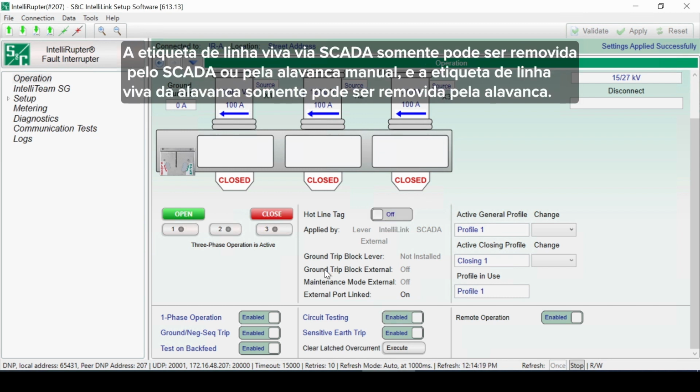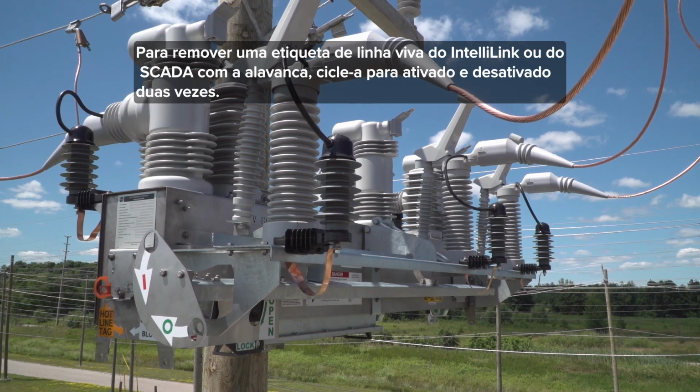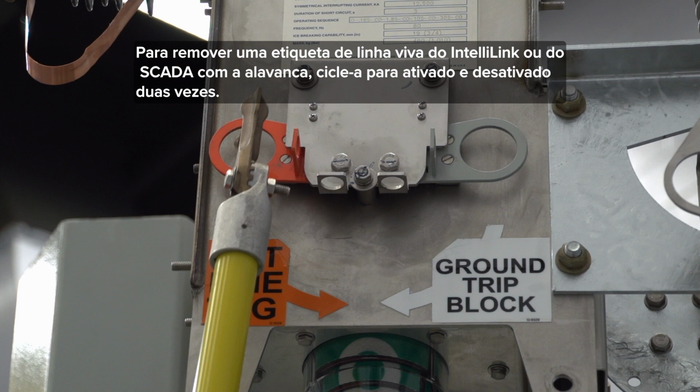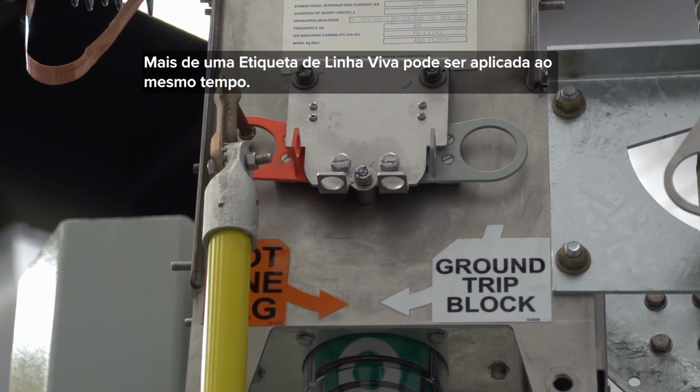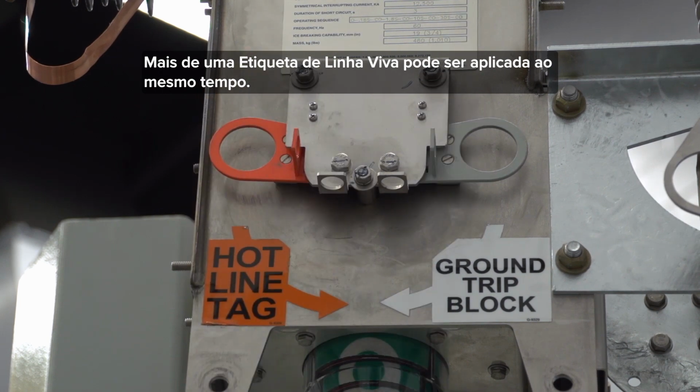The SCADA Hotline Tag can only be removed by SCADA or the manual lever, and the lever Hotline Tag can only be removed by the lever. To remove an IntelliLink or SCADA Hotline Tag with the lever, cycle it on and off twice. More than one hotline tag can be applied at a time.